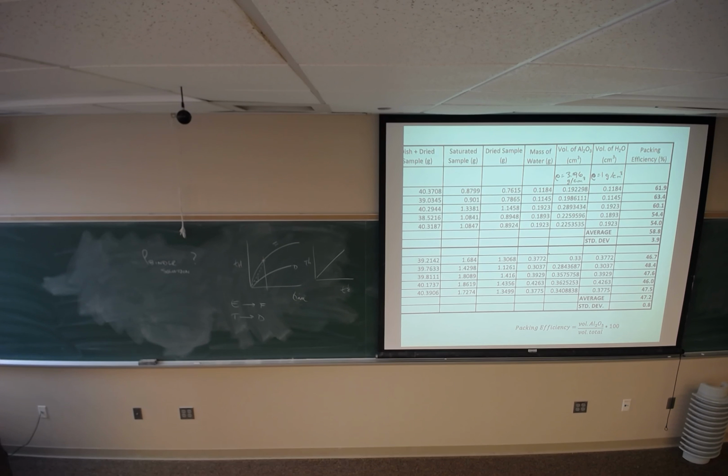I had a senior thesis student once who did specific volume diagrams with alumina. He came back, and none of his measured values matched his calculated values. Because his graduated cylinder, when it said 100, it was actually 96, or 98, something like that. So then all his volumes were off, and he corrected all that in his data. So you should calibrate the graduated cylinder, look at your polymer solutions on the side. Good? That's this week, okay? And next week and the week after, specific volume diagrams is a way to predict ceramic forming processes.